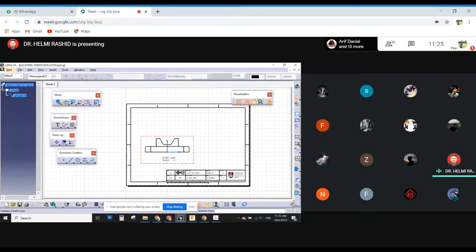All right, so we are looking still into the projection. So you go to the fourth one, projection view. You click this, bring your cursor to the top of your front view and then it will show you the top view. See, right, so you can click this, see top view. And then if you click this again, bring your cursor to the right, it will show you the right view.